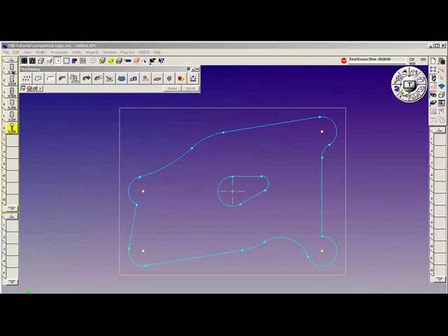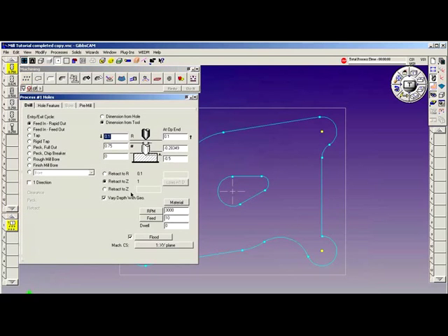So the first thing I do is I bring down tool number 1, the 3/4 inch drill. And this is done with the holes process. I'm going to pocket this part out to a minus 0.5, so I'm going to drill down to 450 thousandths. I'm going to feed in, rapid out. I'm going to take my dimensions from the tool. My rapid approach plane is 0.1. Top of my cut is 0. At up end, I'm going to go to 0.1. And my depth of cut to the tip is going to be minus 0.45. And I'm going to retract to Z.1.